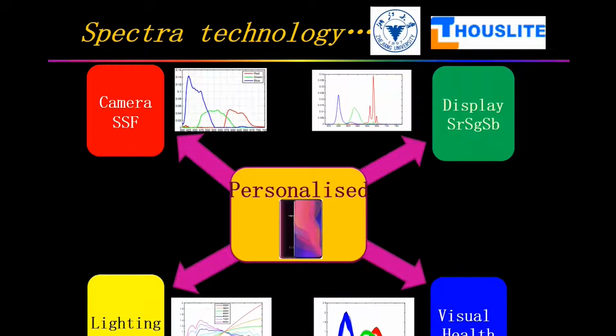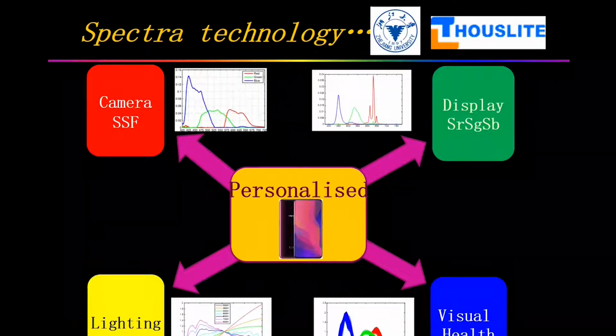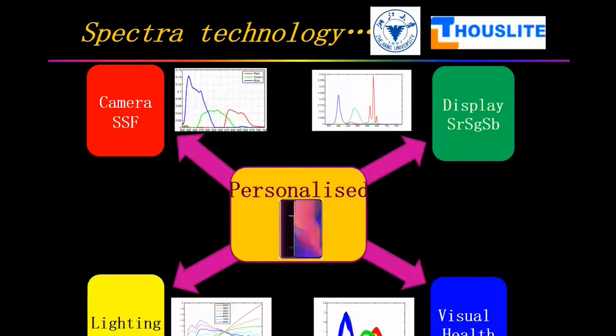The displays are all very exciting, but the problem of the current displays is that they are too sharp in terms of their spectra, their location of the red, green, blue is not quite right. Everybody sees a big difference, okay? And appearance consistency is a problem. So we need to select the right RGB in the right bandwidth and the right peak to give the best combination in terms of least observer metamerism, okay? Everybody sees the colors the same. That is the goal.